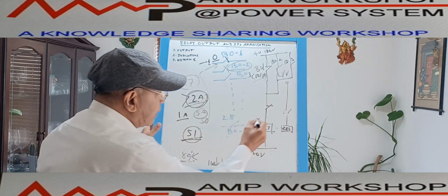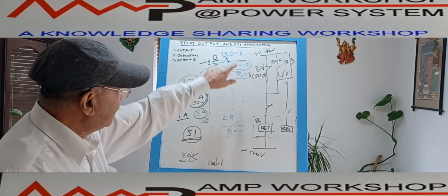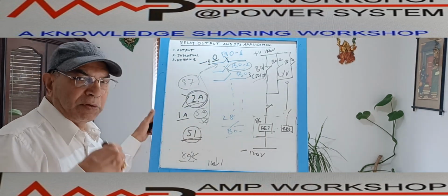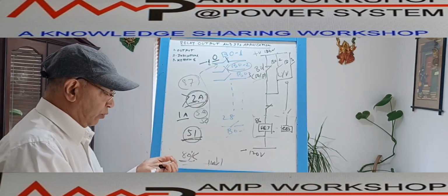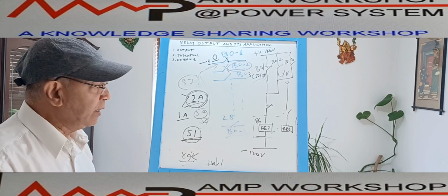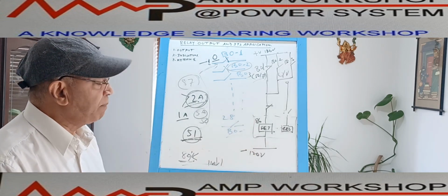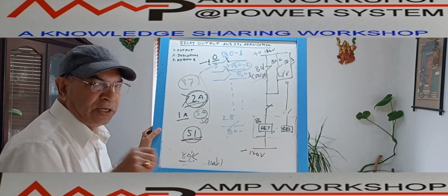This lockout is a separate relay, we have seen already, this is a separate relay, and these are the output contacts of the main protection relay, which we are configuring based on the analog values. This way I can configure the output contact for the protection function.